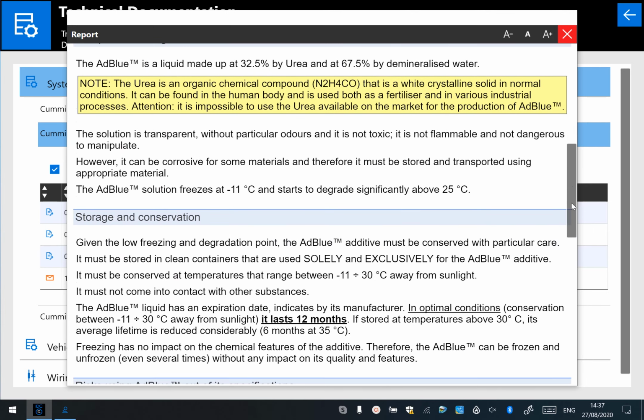A few of the other tabs I wanted to explain at the top. So we've got status. Sometimes switches are put in a separate tab. Other times they're actually within the faults or the sensors in the live data. So there's just a few here that they've put, so you can at least see if the systems are working. ECU info, that's obviously pulling out what it can from the vehicle, and it'll populate whatever it can populate. So again, that's information you can print off to use later.